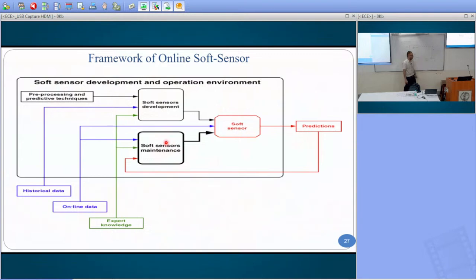But the one question is, this sample comes only every 6 hours, not every time. So you can't correct this model every time, right? The error that you get is only every 6 hours, not every second. You get only one error every 6 hours. So I am taking that error and adding it to my model predictions, to correct my model predictions.